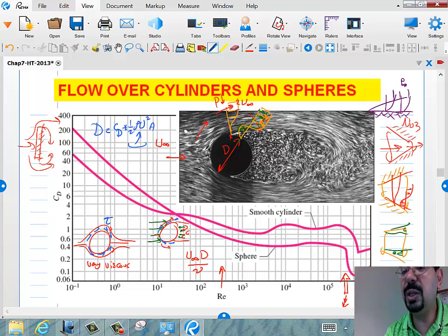You could think of the opposite as a diffuser. So when you go into an area that's getting bigger like this, what will happen? Excellent. The opposite, exactly. The velocity will decrease, and the pressure will increase. So basically, the flow going into something like this keeps building pressure. Pressure is getting higher and higher.